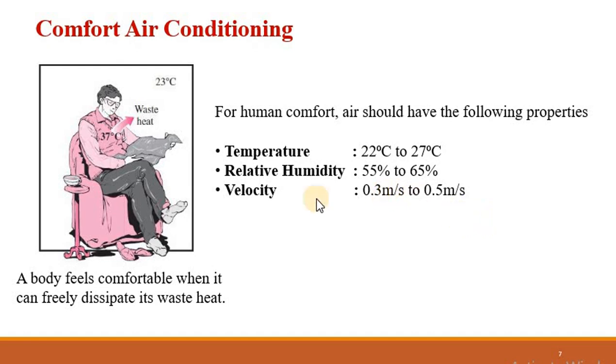So normally it varies along. The temperature range is 22 to 27 degrees Celsius. Relative humidity is 55 to 65 percent. And air velocity is also very important. That is 0.3 meter per second to 0.5 meter per second. All these terms are very important.